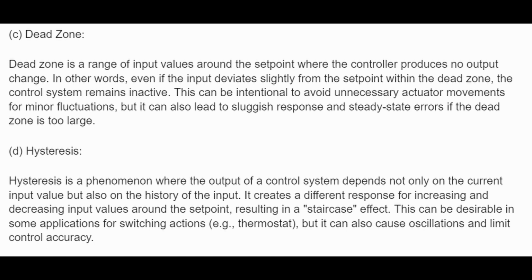In other words, even if the input deviates slightly from the set point within the dead zone, the control system remains inactive. This can be intentional to avoid unnecessary actuator movements for minor fluctuations, but it can also lead to sluggish response and steady-state errors if the dead zone is too large.